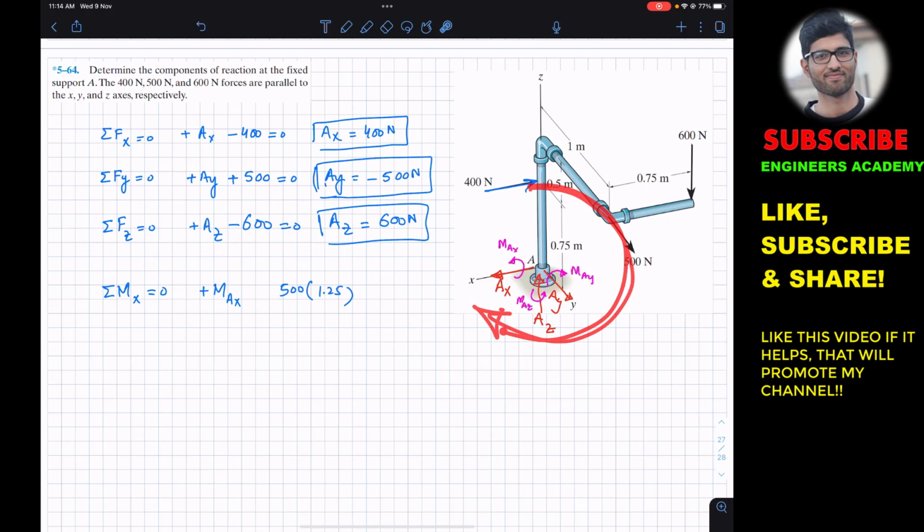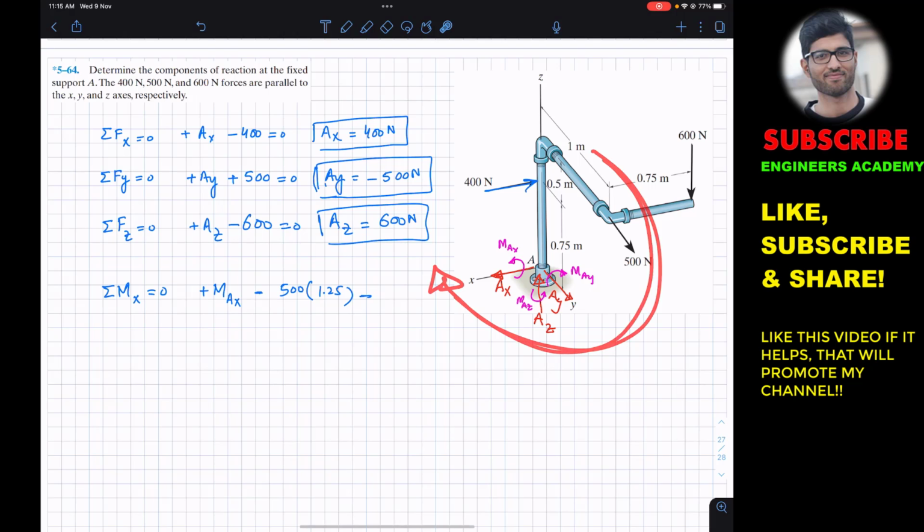This 500 Newton force is producing a moment about the x-axis in this direction. If we curl our right hand fingers in this direction, the thumb will point out in the negative x. So it is producing a clockwise moment about the x-axis. Now this 600 Newton force is also producing a clockwise moment about the x-axis, just like the 500 Newton force. So we will write minus, since if we curl our right hand fingers about the x-axis in this direction, the thumb will point out in the negative x. That is why it's producing the clockwise moment.